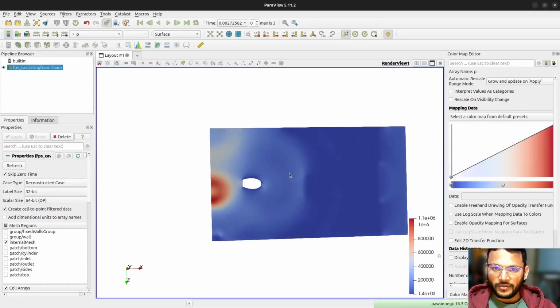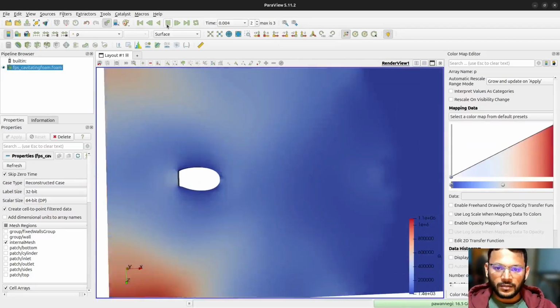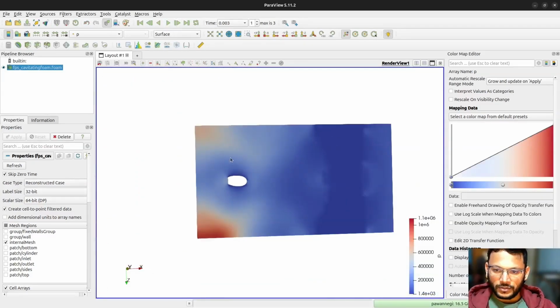Here at the inlet we have some weird pressure, so this should not happen. We should keep this inlet far away from this particular object. Similarly for the outlet and these walls, the domain is much smaller. You should see our lecture on compressible flows to find out the effect when, for compressible flow, the object is very close to the walls.